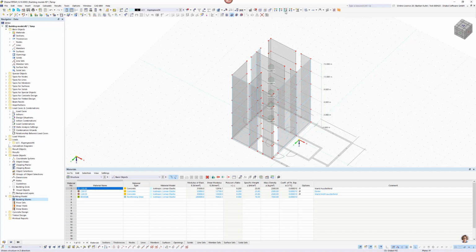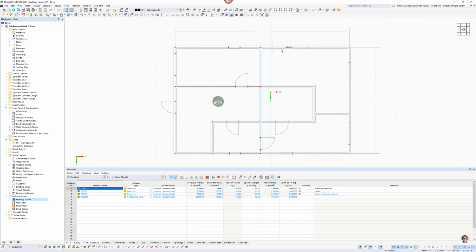And of course, I said in this case, we will need a few more posts and maybe we will put some kind of drywall or a masonry wall or something like this on this part in order to reduce the free span, because if I do not activate these walls in here, I will probably get problems with the deflection and the vibration of my structure. So I will proceed with the columns.